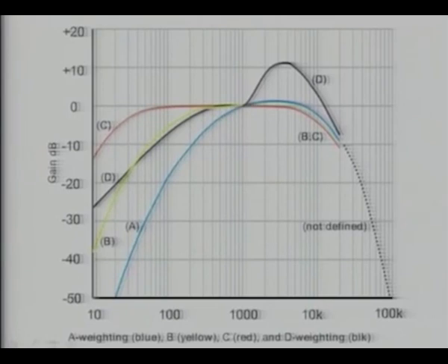And these curves have been developed based on how the ear perceives sound at different frequencies and at different levels. Based on some statistical samples, people have developed these curves, and now they are the industry standard. A lot of environmental agencies, say in India, the United States or Europe, actually enforce that if you're trying to solve noise-related problems, you have to weight your measurements based on some of these curves. So that is the purpose.